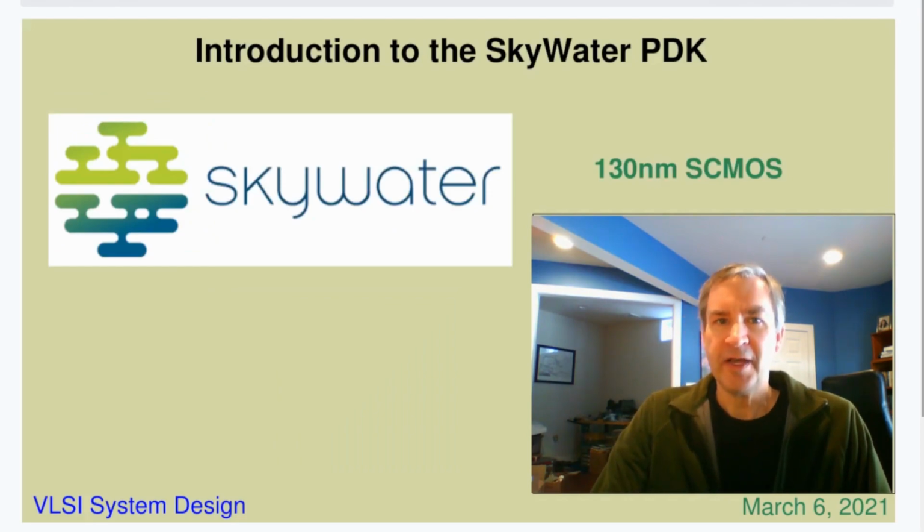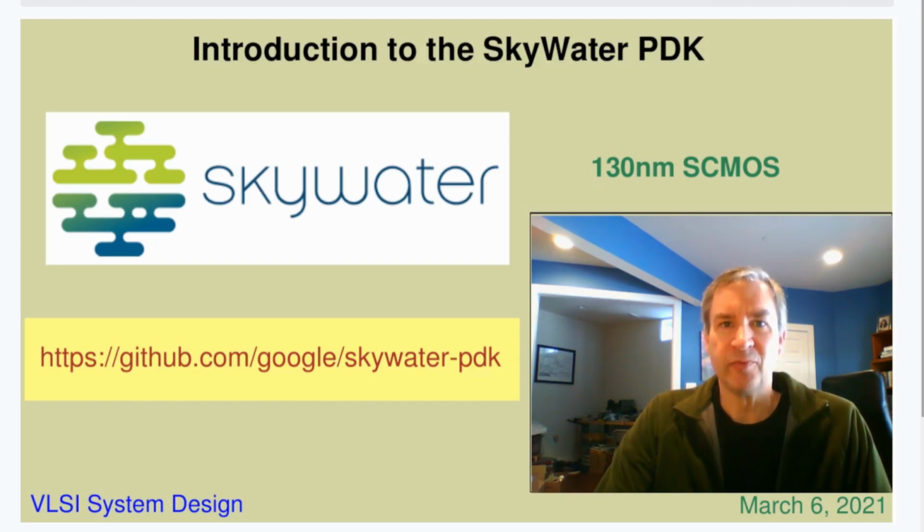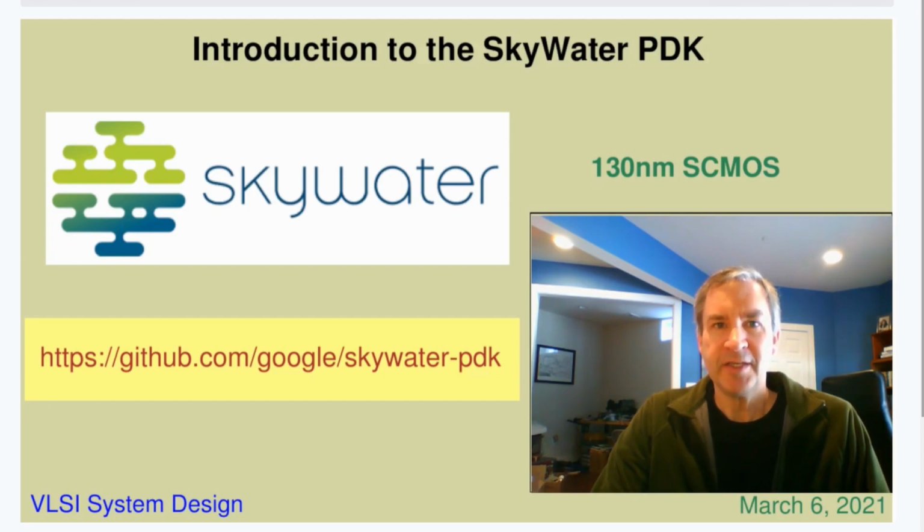The SkyWater 130 nanometer Open PDK changes all that. The process has been completely open sourced with all design rules, layer definitions, device definitions and models, device layouts, and other critical process information made available to the public. For the first time, it's possible to work up libraries and setups for open source tools built around a real manufacturable process. Since everyone can see the PDK, anyone who has or uses an open source tool can make it compatible with the Sky130 process or contribute to that development. This has already happened with the SkyWater PDK, as I will describe in a moment.